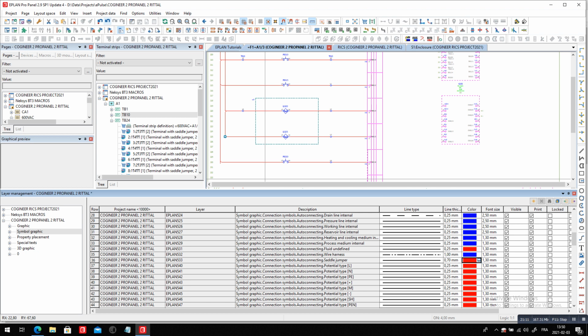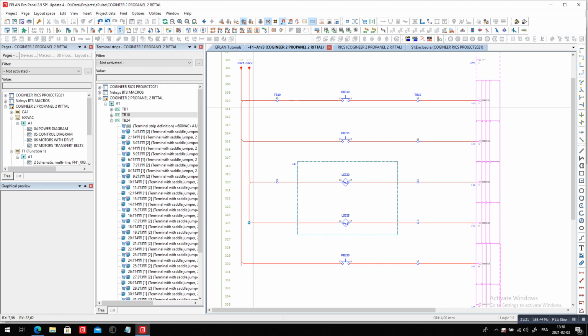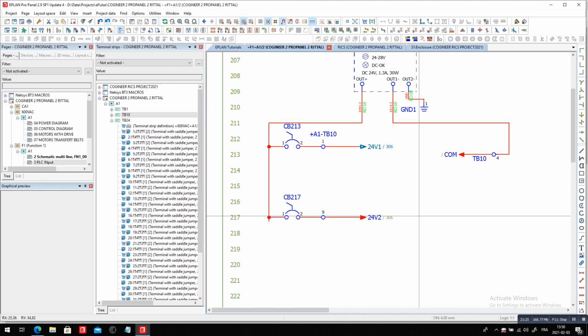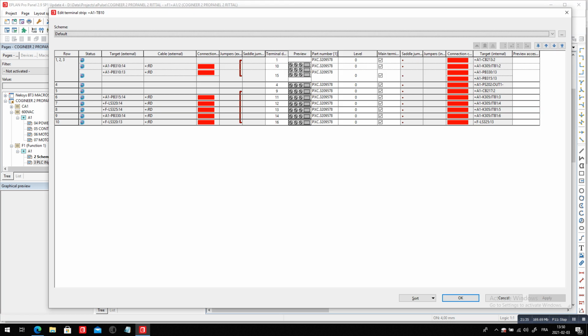And when I do so, a jumper is actually created, and you will see on the previous page that we don't have any jumpers at the moment, so nothing really happens at the moment. So let's reorganize our terminal strip edit here, and let's sort this by jumpers, a little bit like we said earlier, right? Sort by jumpers, or in this case, let's just split this guy, sort by jumpers. And you will see we have these organized like this.